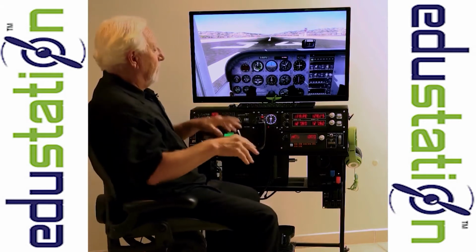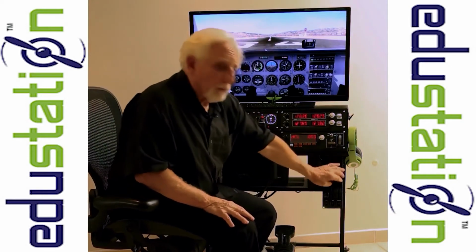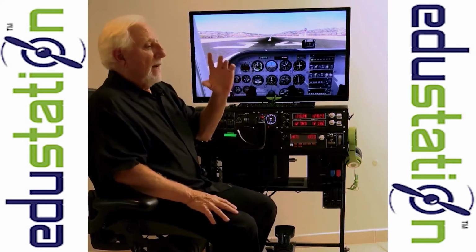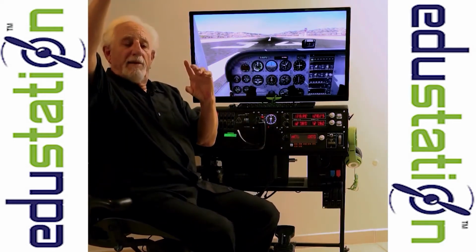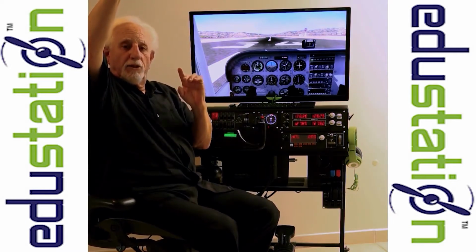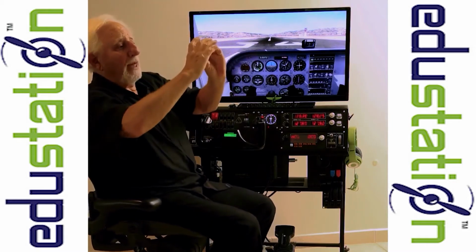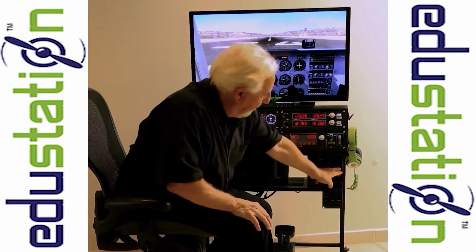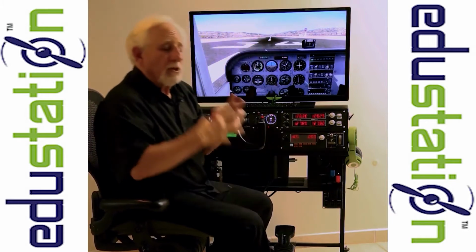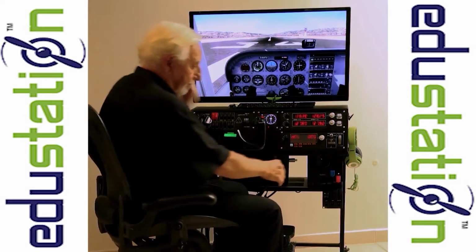When we're on the ground and the air is very dense, we want to run the airplane at full rich, all the way up. But when we get to 10,000 feet, the air is getting less dense, less oxygen. So in order to have the correct ratio of fuel to air, we use this lever to lean out the engine so it'll continue to make power as we go higher in altitude.